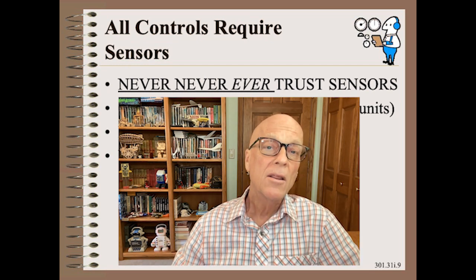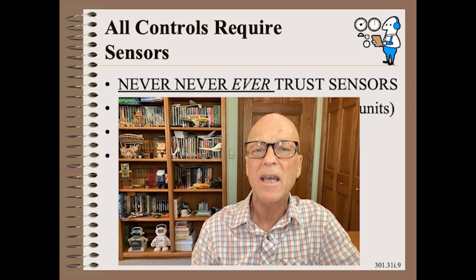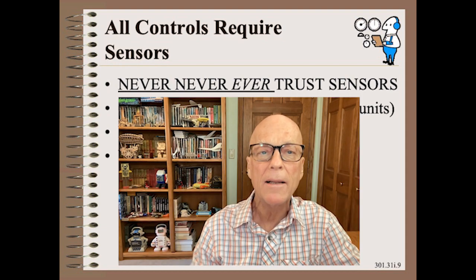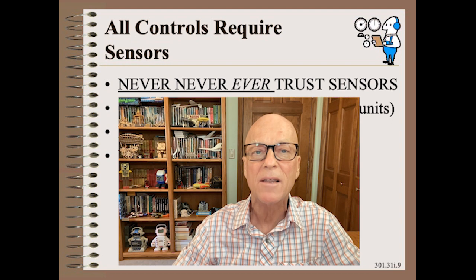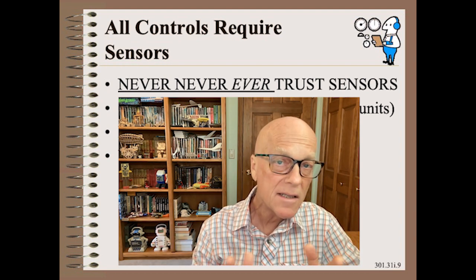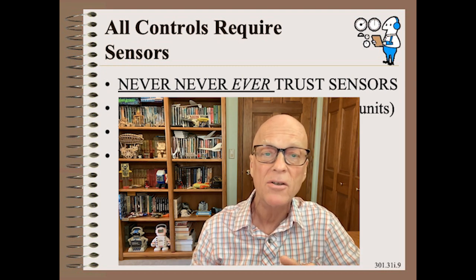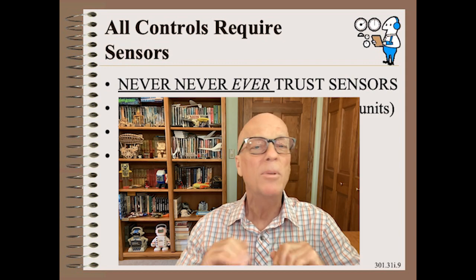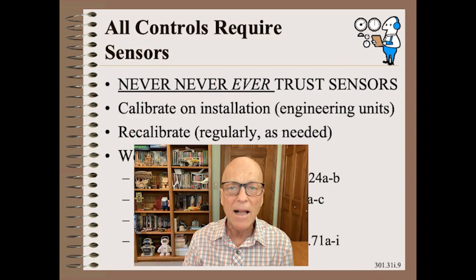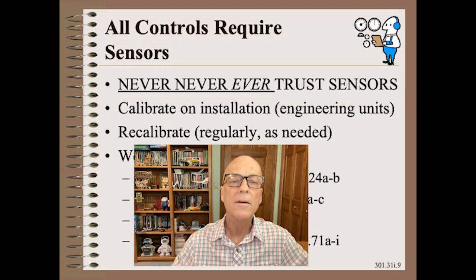The reason being is that if you do, you will eventually get burned, perhaps sooner than you think. The primary sensors in airplanes are called indicators because they are only an indication of reality. Any pilot who blindly trusts them without cross-checking with other sensors unnecessarily risks their own life as well as the lives of their passengers. But the solution is simple. Calibrate, recalibrate, and cross-calibrate regularly.